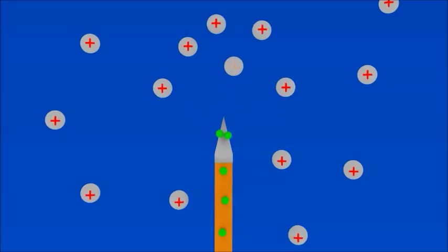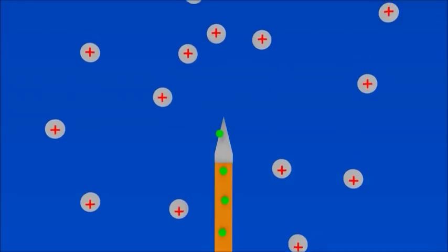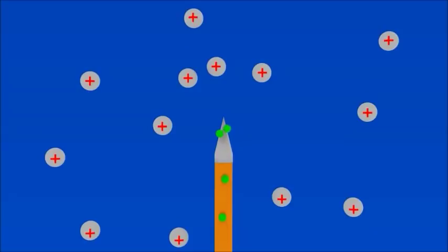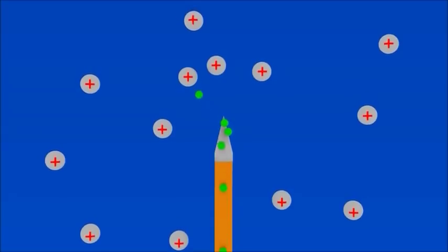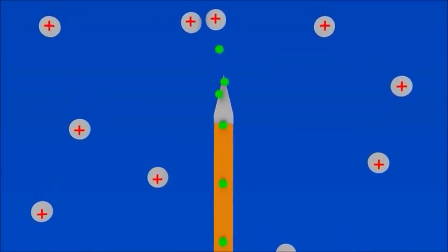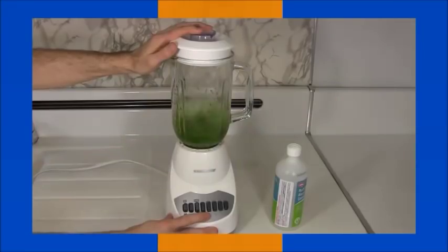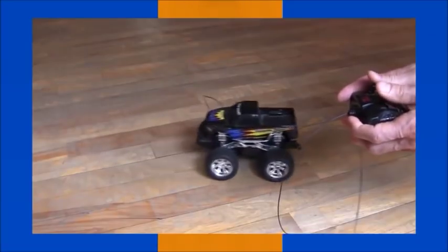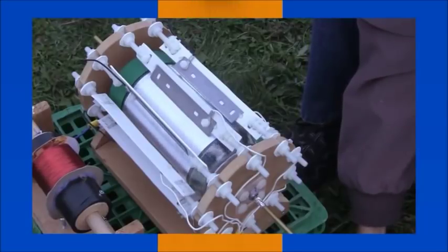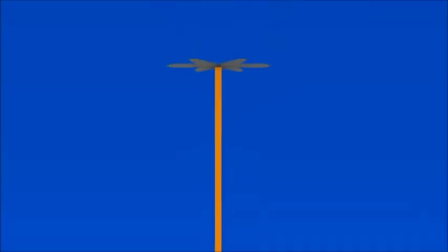It's strong enough to remove the negative electrons from the sharp point, where they neutralize positive ions. But due to the voltage, there are fresh positive ions moving downward and fresh negative charges coming up from the wire. We now have electricity flowing through the wire. The electric current in that electricity is very weak though. We didn't measure it, but from my experience with electrostatics, I'd estimate it in the low microamps, or more likely even lower. That's not enough to turn an electromagnetic motor, one like you use in everyday life, but it is enough to turn an electrostatic motor, like this Corona motor.